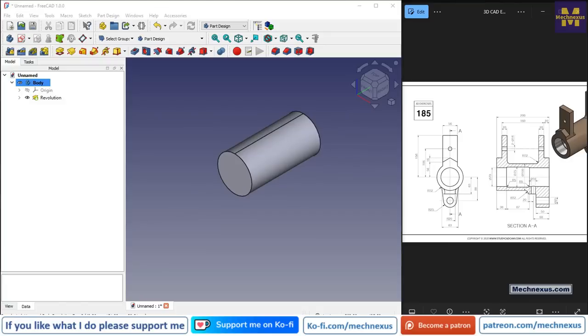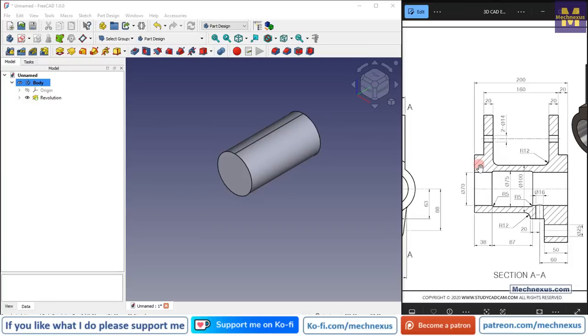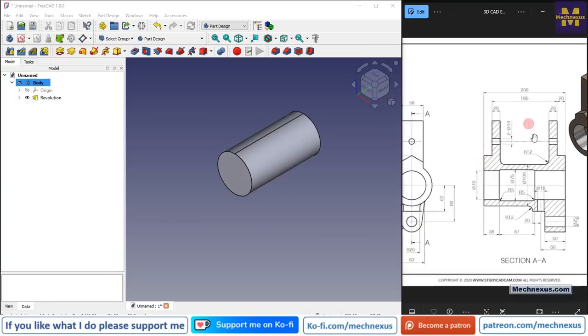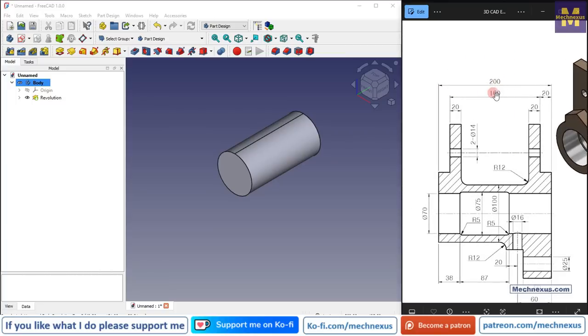Now we will create the next feature, and for the next feature we will create a datum plane at a distance of 20, because our total width is 200 and this is 160, so here 20 is given.